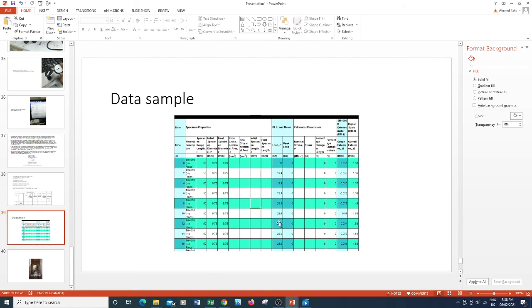Now this is the real data collected from the data acquisition. This is the force, and this is the specimen elongation, delta L, measured by the gauge. You have the initial gauge length, which is 50 millimeter. What I need to do is look at the maximum delta L, and add this delta L to the initial gauge. This will give me the final length of the gauge.